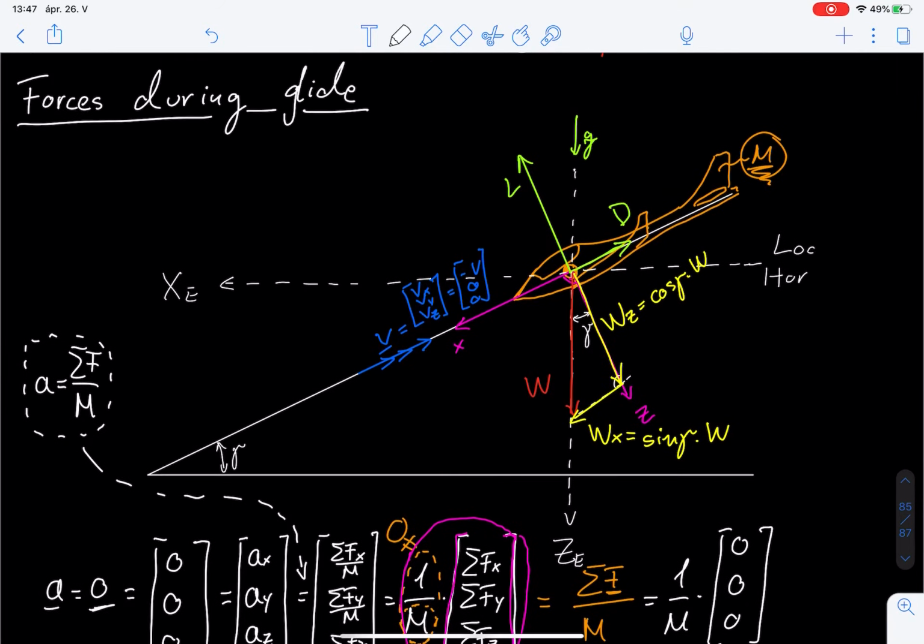Okay, now as you can see, we can make some simplifications. So the velocity is present in both terms, the surface area and the half of the density is as well. So what we're left with at the very end is a drag coefficient over the lift coefficient. And so let's express it in a final form. So what we received in this whole discussion is that the tangent of the gamma, the flight path angle, is going to be a function of the drag coefficient over the lift coefficient, right?